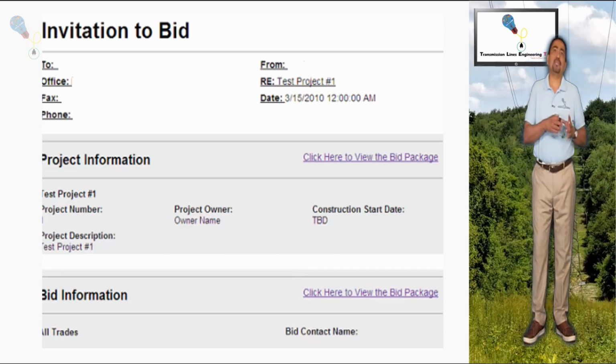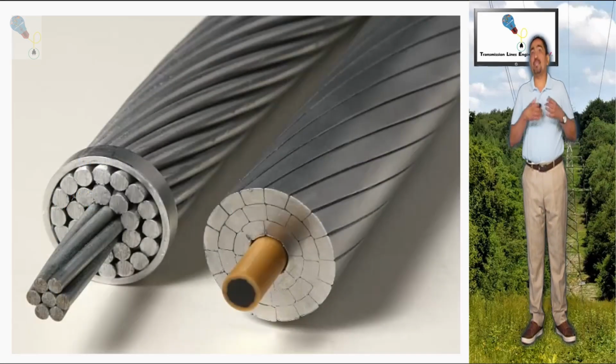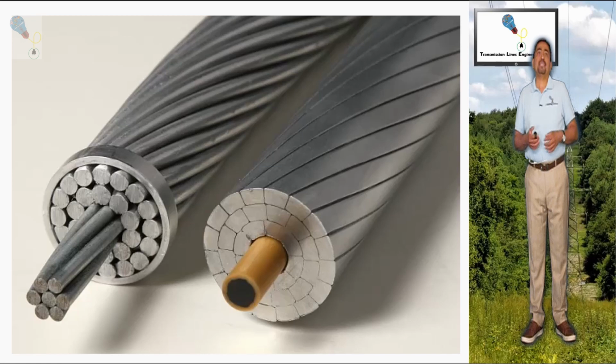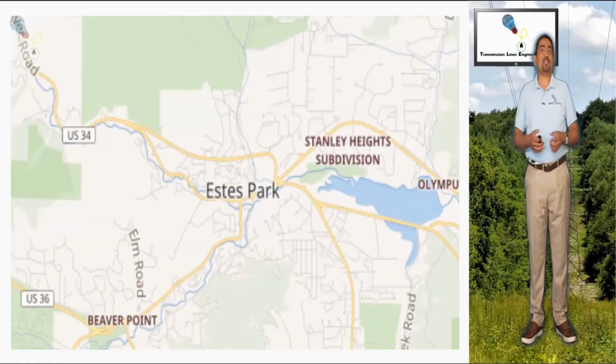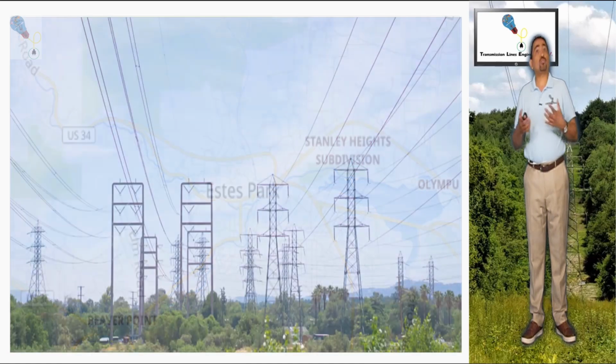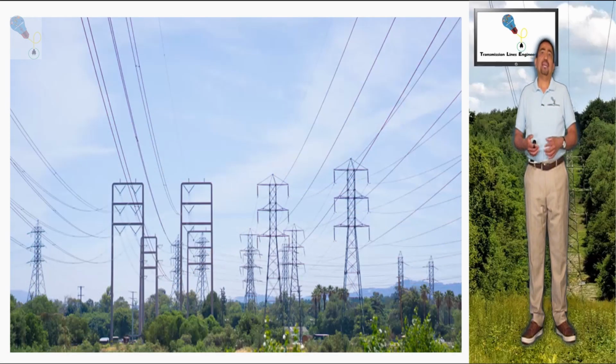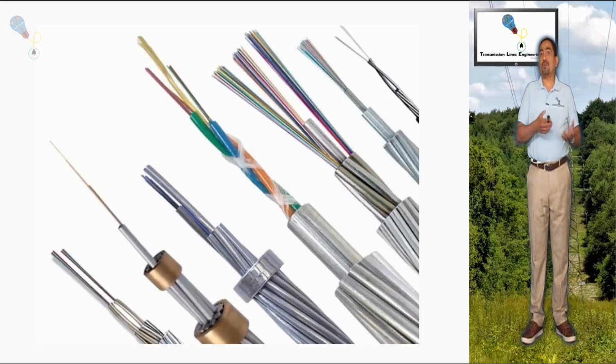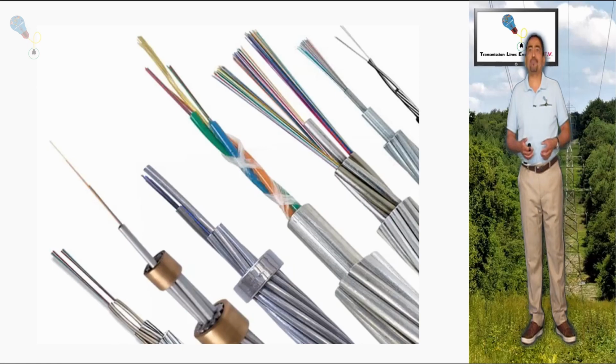This document describes the conductors to be used, the coordinates of the deflection points or PIs in the line, the structure types to be used, limitations for structure locations, the need or not of fiber optic, OPGW, etc.